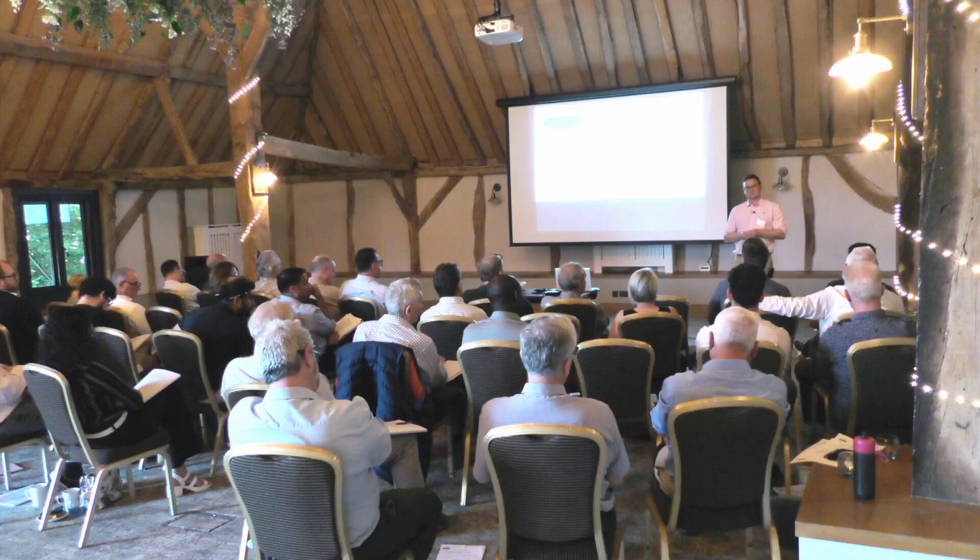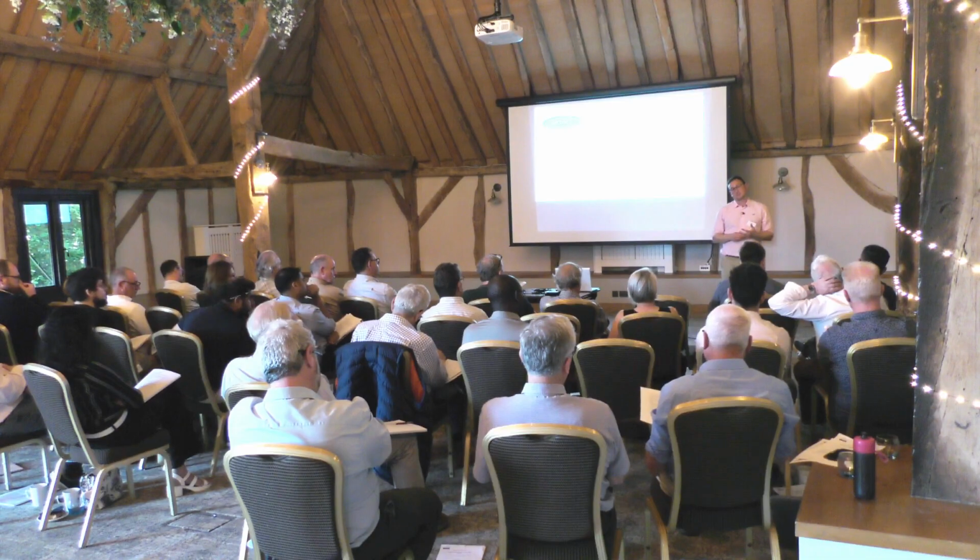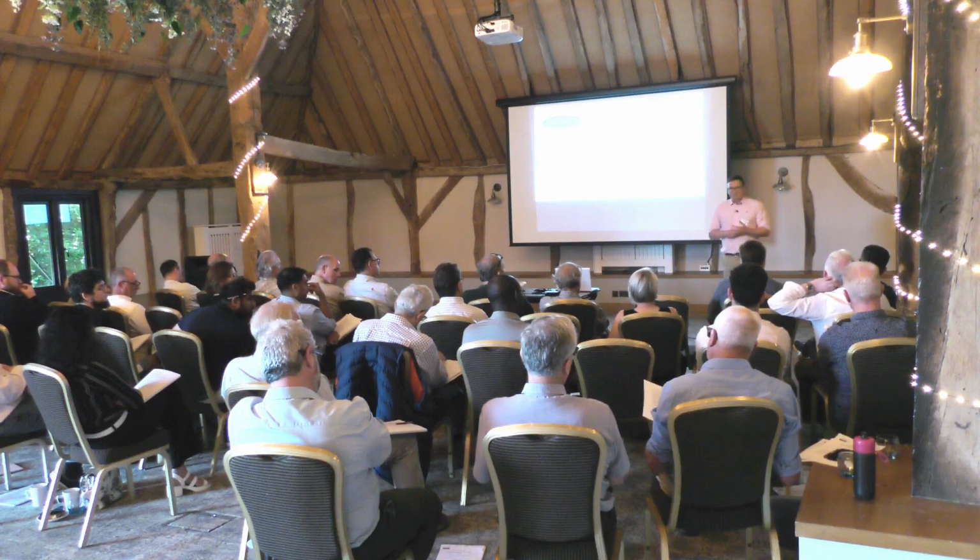Doesn't help when you're doing it retrospectively. Are you doing a survey on an existing building? If it was an existing building and it's not having building works done, then the building regulations wouldn't kick in. It would be an existing building itself that you're surveying. Unless the building works had already happened, like the provisions of new bathrooms, etc. So if you're looking to make what's known as a regularisation application for existing work that's taken place in the past, we'll come to this at the end, then the same requirements would be kicking in, but it's about the requirements at the time that the works took place. We'll come to regularisations at the end.